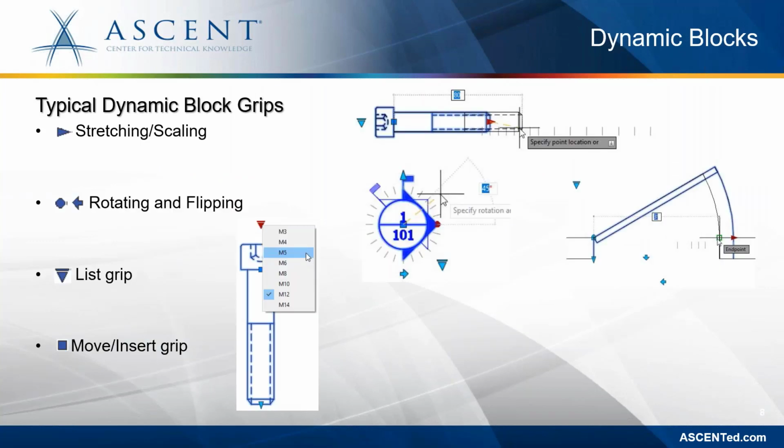Now, let's quickly get to know about the various grips. The half arrow grip, which is without the tail, is the lengthen, shorten grip. As the name specifies, it can scale and stretch a block. As you can see on the screen, there are line marks displaying along the right side of the bolt. These are preset increments for scaling and stretching, set in the block definition for the required standard sizes. For example, you can set those increments for standard bolt lengths or window lengths.